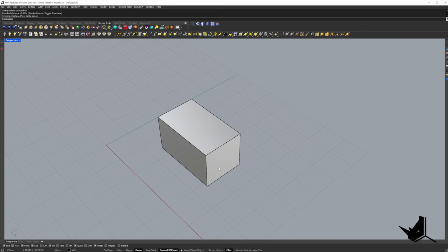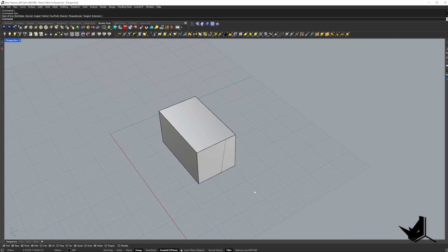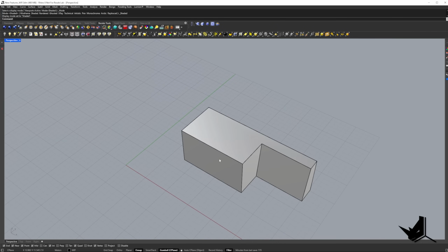However, when you have some kind of line, so let's say we want to draw some kind of curve on this surface like this. Now if I use this command, it's going to ask me to select the surface to push or pull. Simply click here, and just like that I can extrude it outside. The same thing would happen if I do it, let's say somewhere around here.